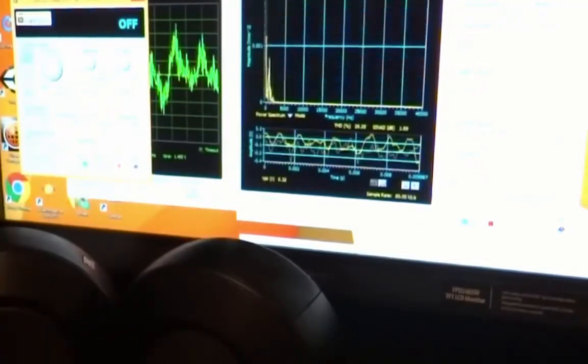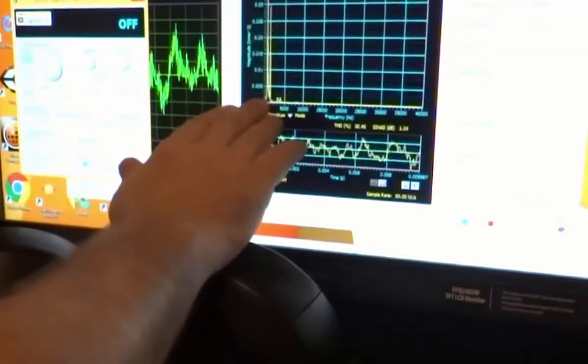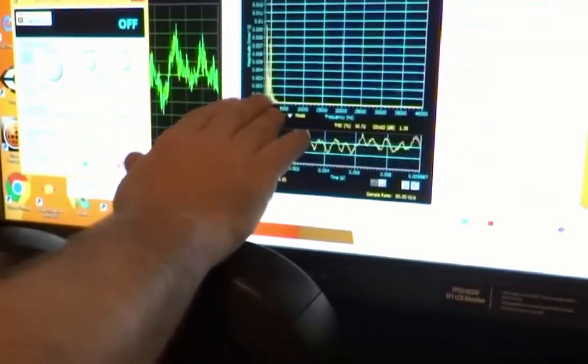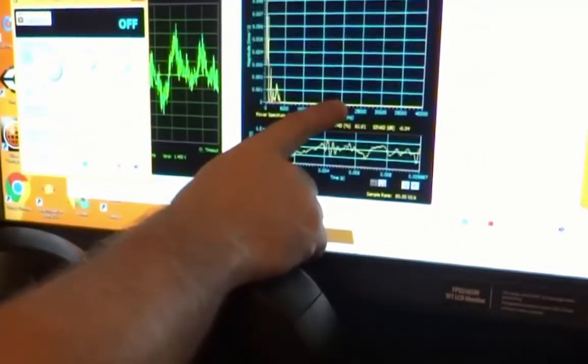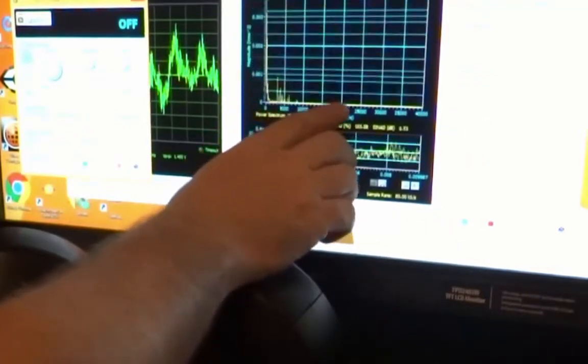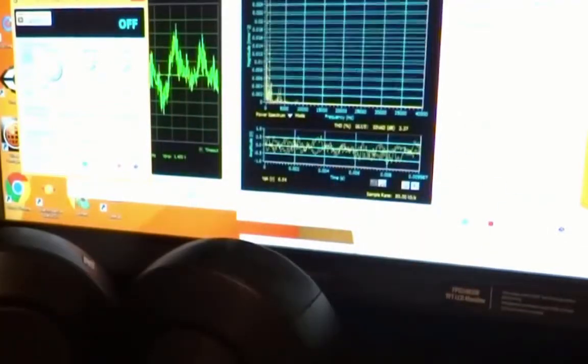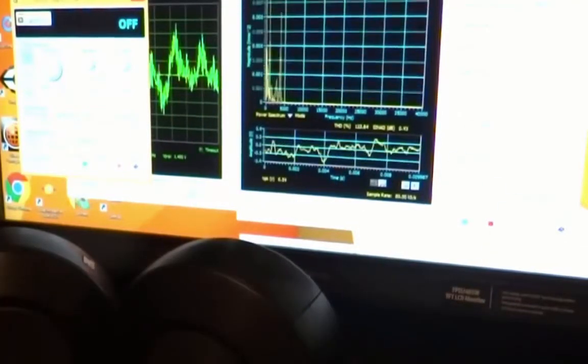So you need to pick a carrier frequency so that when you go through the modulation process and then run it through a second multiplication of the cosine to demodulate it, when these copies shift back to the middle, they don't overlay on top of each other.